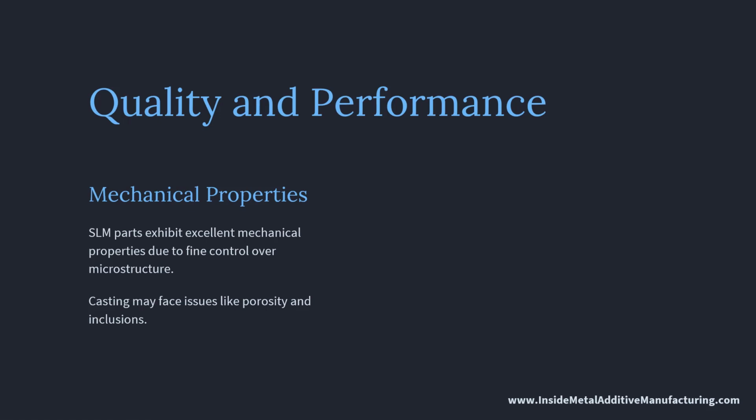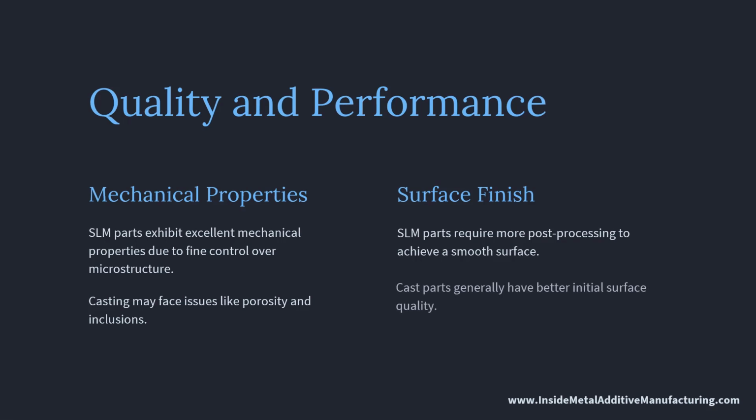If we consider surface finish and post-processing requirements, SLM parts often require significant post-processing to achieve a smooth finish. Cast parts generally have better surface quality right out of the mold, dependent on the mold's finish, but they may still need further finishing processes.